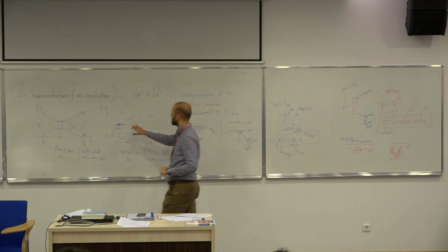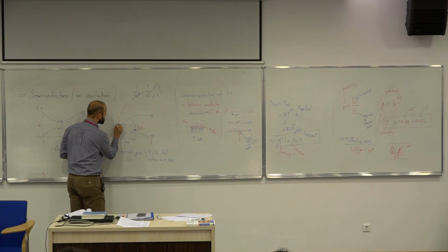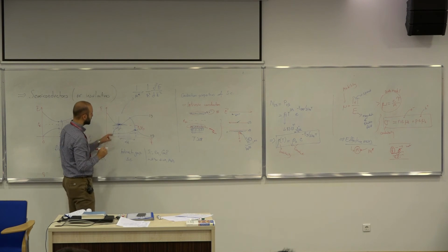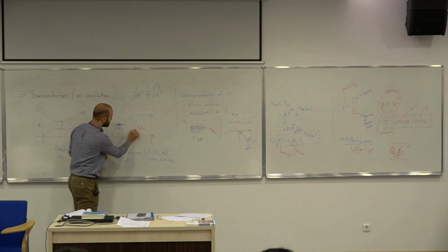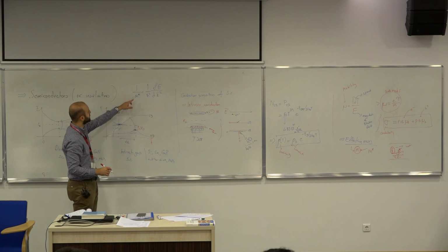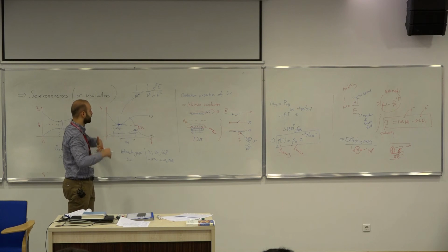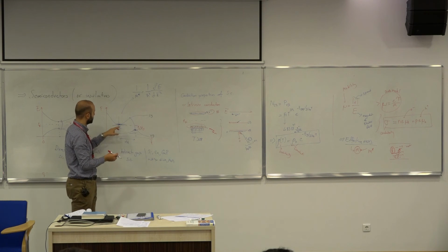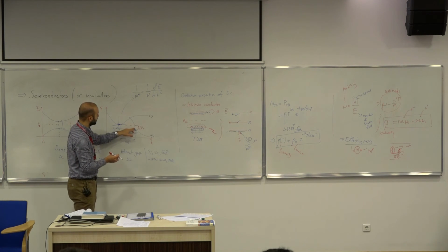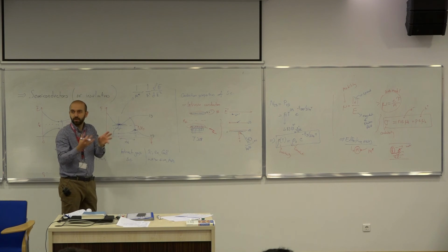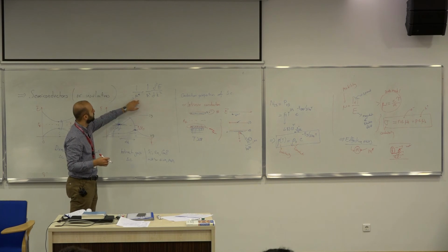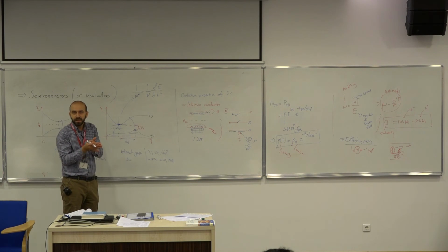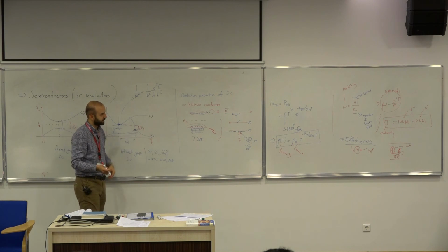Here the case is extremely similar. I'm focusing on the electrons that are at the edge of the conduction band and the valence band. And rather than saying, let me take the free mass of the electrons and use all the forces and all the potentials that are acting on the electron, I say, well, let me define an effective mass and use that mass in my calculations.